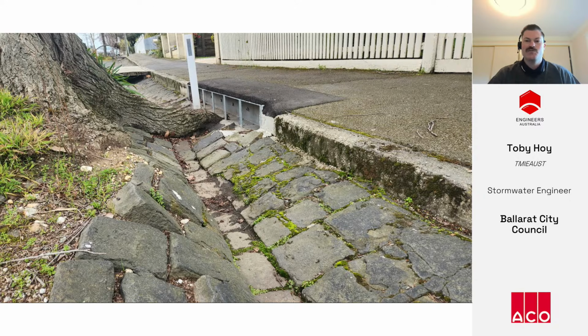While this doesn't solve the issue completely, this allows about another 150 millimetres of water to pass around the tree root with minimal disturbance to the surrounding infrastructure and at a cheap price compared to our other options. It also allows many more leaves to flow with the water around the tree root rather than banking up and blocking the water further. Our channel is anchored into a concrete block poured behind with an asphalt surface to match the rest of the footpath around the concrete and to match the area's infrastructure in general.